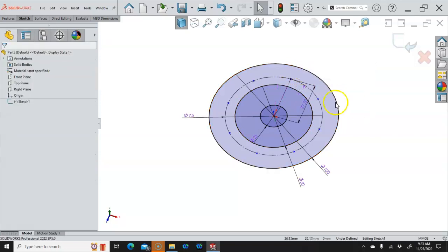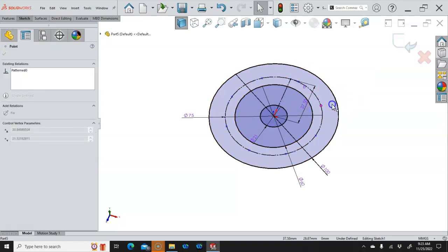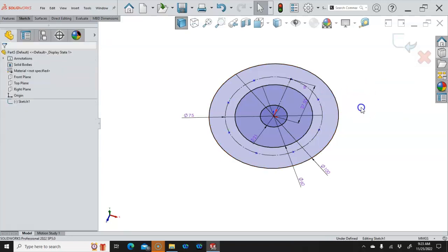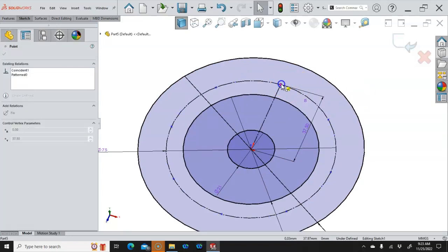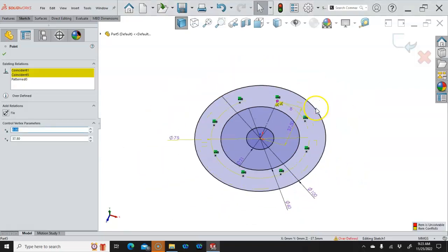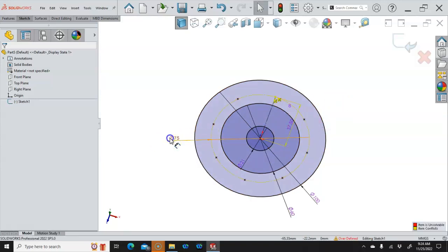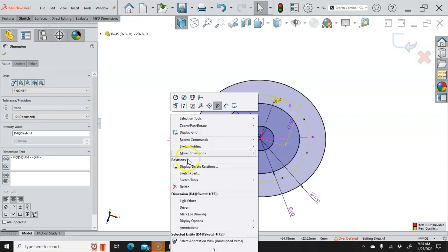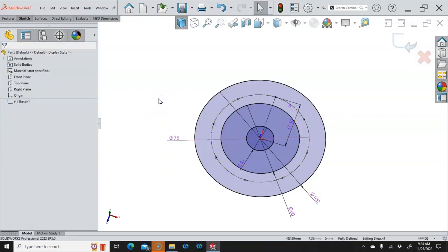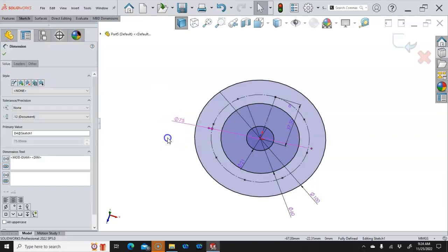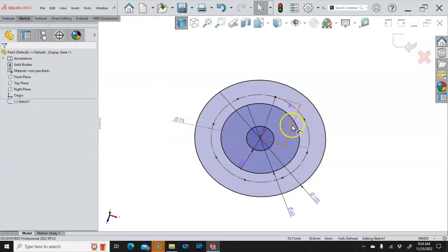We'll just make the line vertical, and maybe the vertical and the other coincident were the issues. So sometimes we just have to diagnose these. So still not liking that. Oh, let's go the other route and make the base circle driven. All right, so I have the diameter of 75, but when I dimension the 37.5, I would have to pick one of those because they're in conflict. All right, so that's my base sketch.